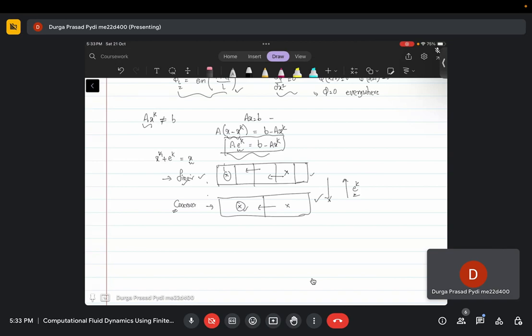So basically you have some original problem and then you formulate a different problem and solve it on a coarser mesh, and this coarser mesh should give you some idea on how to improve your accuracy on the original mesh without actually solving the original problem.